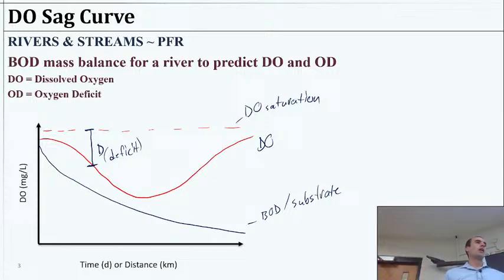Ultimately what we're aiming at with this whole analysis is to understand what kind of deficit we have at different times, and how bad it gets at the worst time. Anytime we have a discharge like this, we will typically have one spot in our stream or river, because we're modeling this as a river. We discharge wastewater into a river, it's flowing, so it's kind of like a plug flow reactor. At what point is the oxygen going to be at its worst? Because that critical point, or maximum deficit, is where we have to make sure that biological life, all of our ecosystem services, the things we want to maintain, are still good. That meets our criteria of protecting intended uses. So we want to design our system to make sure that at that deficit, we're not killing fish or harming parts of the environment. This is how we can tell if that's going to be true or not.